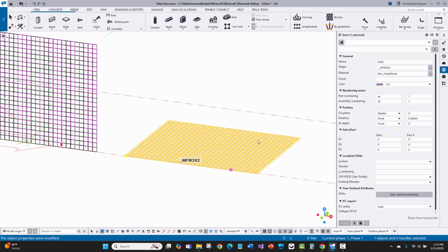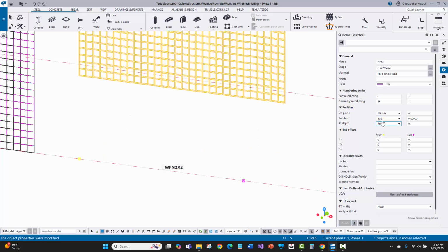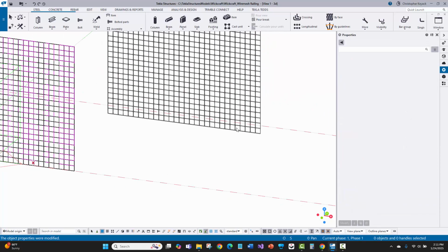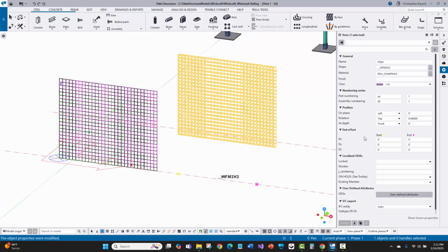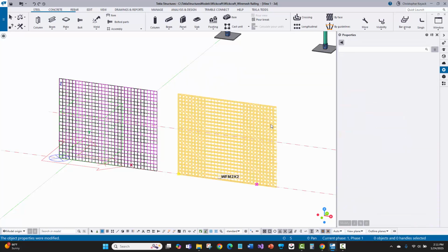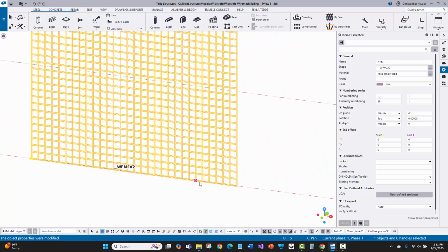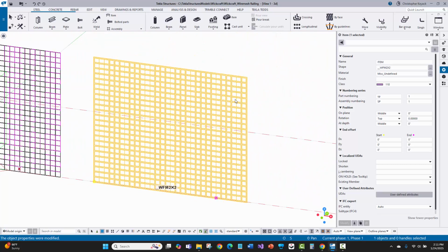Now look, here's something I don't like: it's doing offsets in a way that I don't really want. I do want this at top, but then I'm trying to mess with this. Let me just see what this does. So see, that just changes the left and right, and it's not exactly positioned where I wanted it. It's almost like it took the center of that when I leave this all at middle. And I'm like, oh man, okay, there we go. Now it's back to the position. So the position properties didn't work exactly 100% how I expected, but let me switch this back to middle and see if that still keeps me there. Okay, great. So it keeps it centered thickness-wise on the bars, but now the material is going upward. So everything looks fairly good to what I wanted.